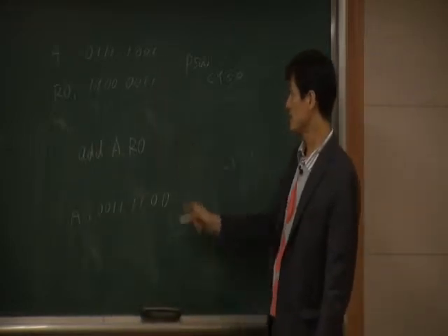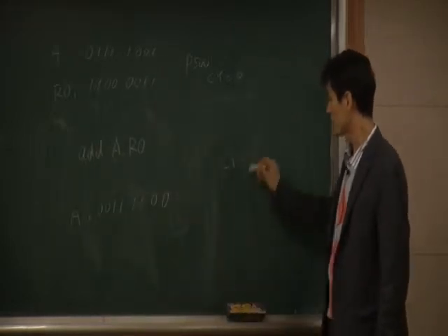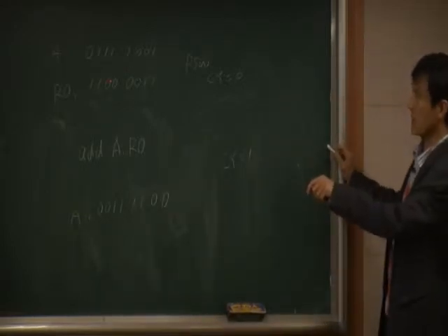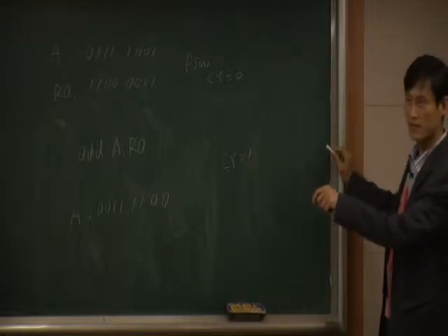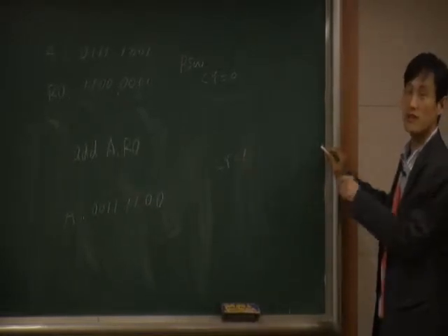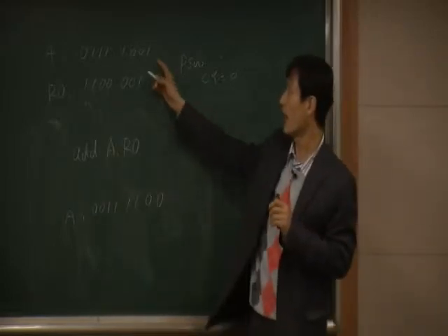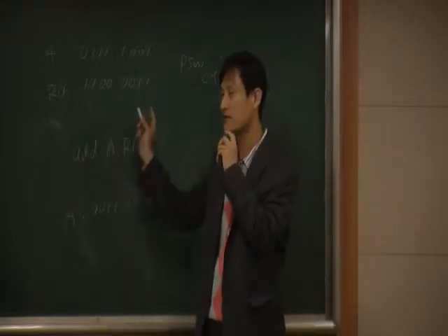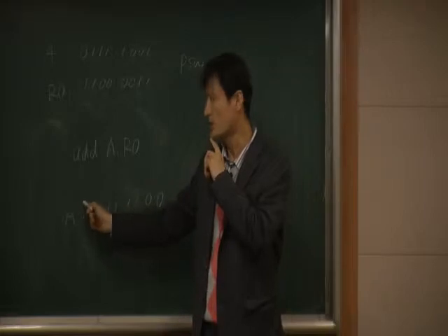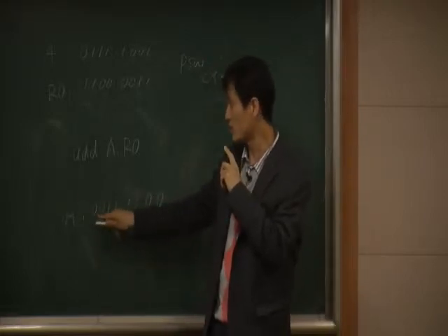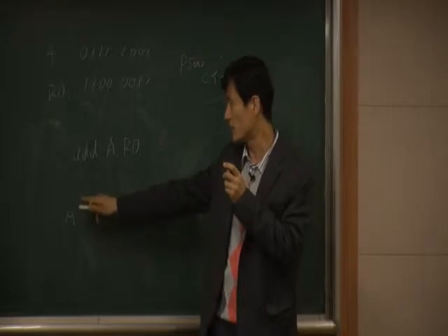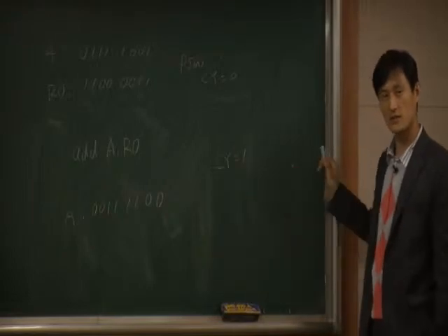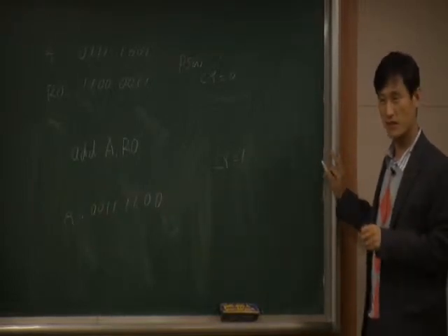When you add these two, in fact, the carry flag is up, okay? Because in our addition, the output becomes 9 bits, right? Because these two are too big, too large a value. So when you add these two, the output becomes 9 bits, okay? It has to be 1 here also, 9 bits. But since our accumulator is just 8 bits, this first one goes away, but instead you have a carry flag, okay? So this is going to be the result when you do add.